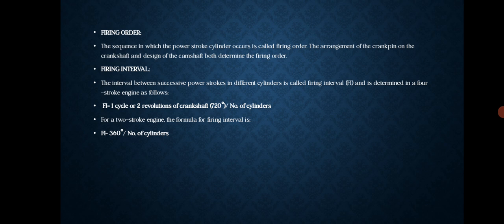The two-stroke spark ignition engine does not have a separate lubrication system, and normally lubricating oil is mixed with the fuel. This is not as effective as the lubrication of a four-stroke engine. Therefore, the parts of a two-stroke engine are subjected to greater wear and tear.